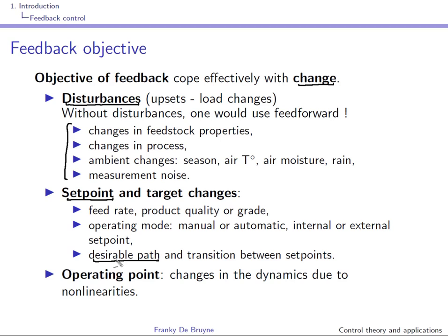A third source of change is a change of operating point, and this source of change is often forgotten. It comes from the non-linearity of the process. If you change operating point, you'll have a change in the dynamics.